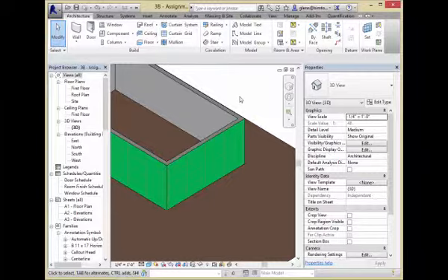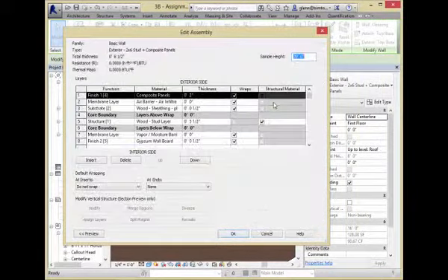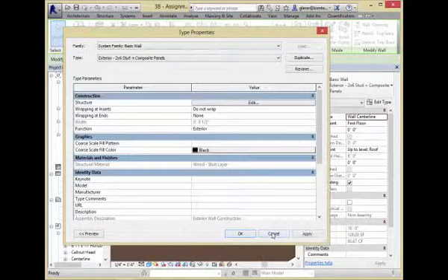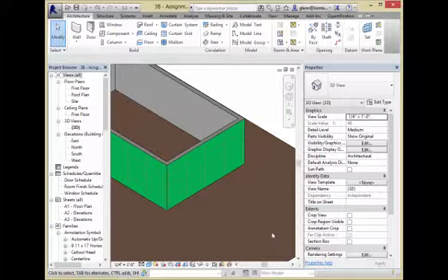In fact, just so you know, it's a really good question. Even on these walls, you'll see there are materials that have names like air infiltration barrier, but they're 0 thick. So why do we bother putting that in there? It's just so we can report the area of that, and later you can include that as part of your estimate. So this whole thing with the wall types gets to be really, really cool. That's the basic rundown on walls in terms of getting going.